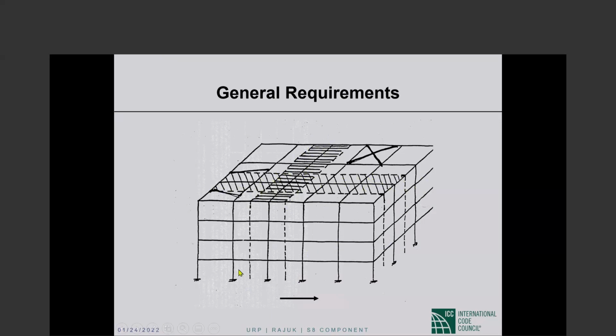Okay, so this strip is taken from panel center line to panel center line, and that strip also is taken from panel center line to panel center line. Here I was trying to show that if the column layout is not exactly symmetrical and everything, then instead of a straight line, you may end up with a line like that. Your panel center line may look like that if the column layout is irregular.